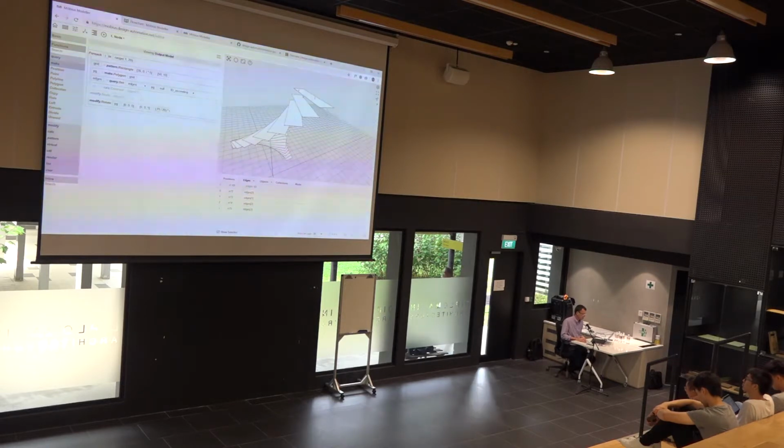So I'm going to scale this edge up. If I scale it around the origin of 0, 0, 0, the edge will also move. If I want to scale the edge and I want it to stay in the same place, just get longer, then I should make my scaling have the origin right in the center of the edge. If I scale around the center of the edge, then the edge won't move, because you're just making it longer.